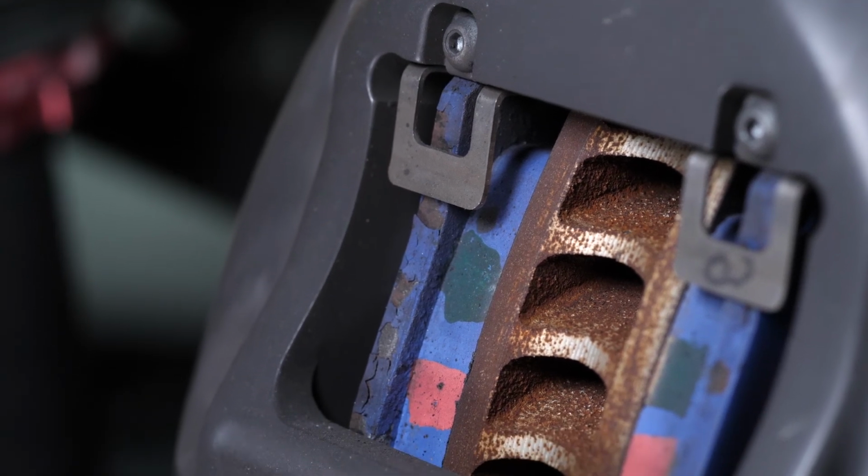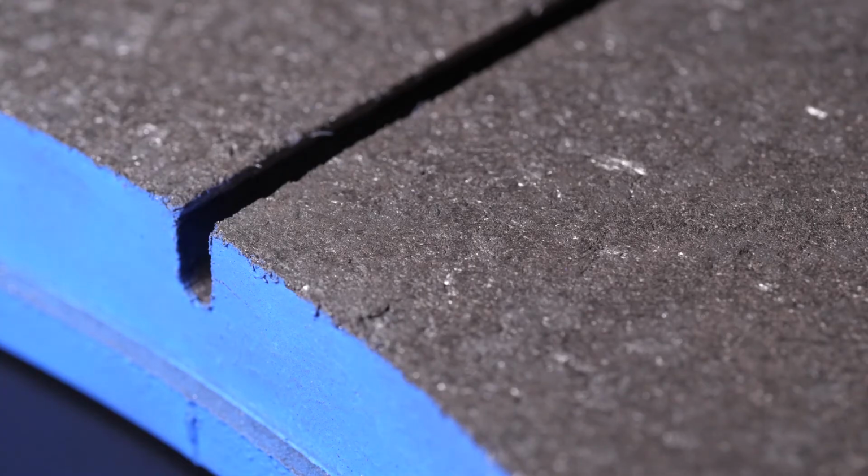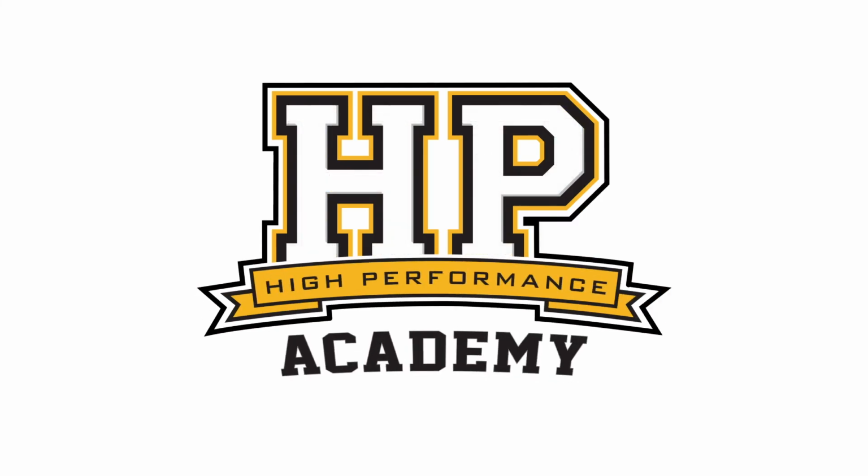Brake pads are the interface between the caliper clamping force and the spinning brake disc. The friction force, and therefore brake force, is directly proportional to the coefficient of friction at that interface, which is mostly a result of the pad compound.